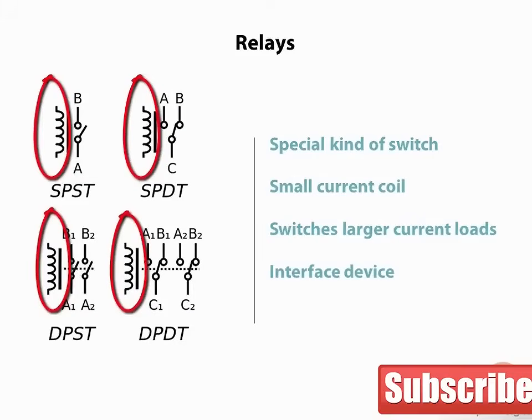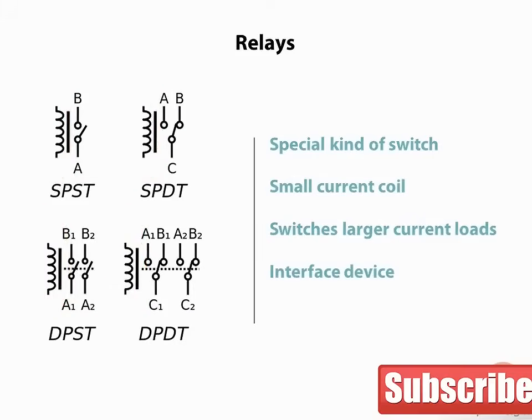When selecting relays, you will need to consider that the coil voltage is compatible with your electronic circuit, and also that the current and voltage rating of the contacts of the switches can handle the load you are switching.